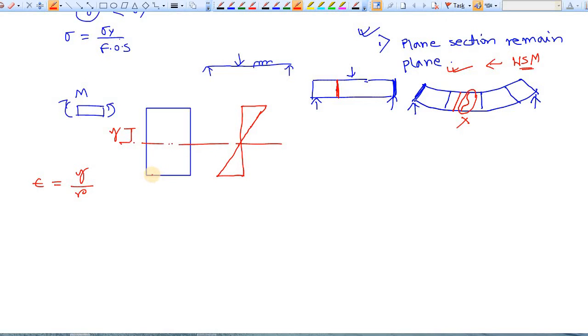Now, instead of using this steel or aluminum section, let's use a reinforced section. What is a reinforced section or singly reinforced section? At the top there is concrete, and at the bottom there is also concrete, and also there is some steel reinforcement like this. But we neglect this whole concrete which is in tension. So now the section looks something like this.